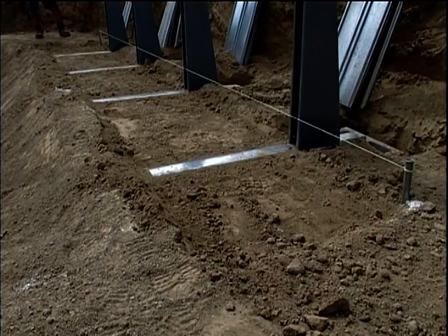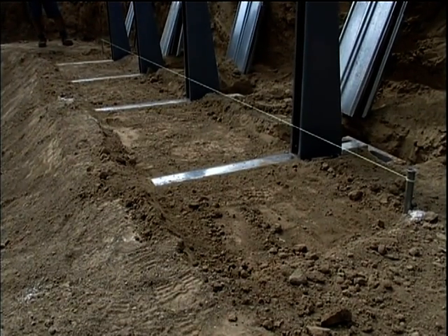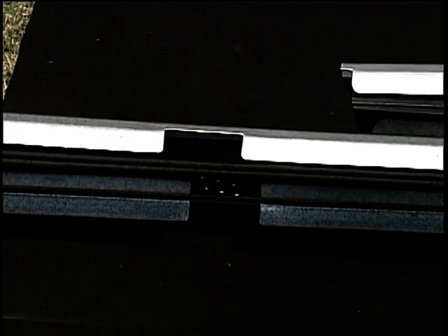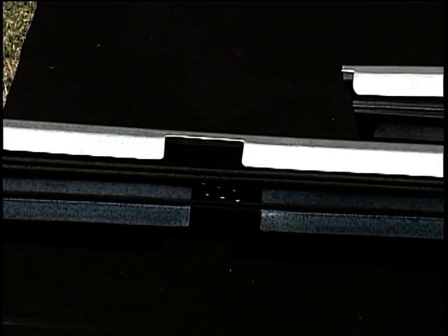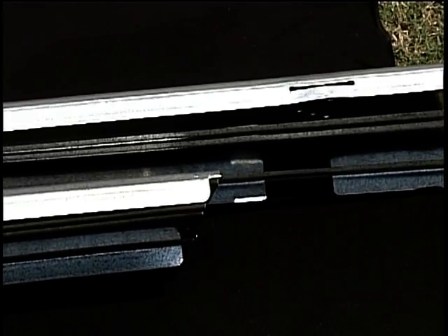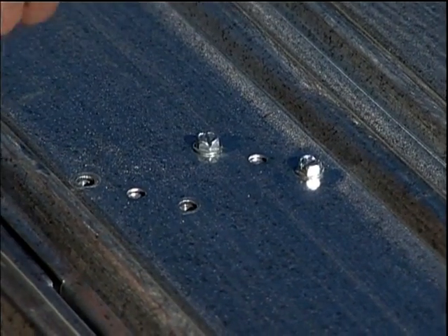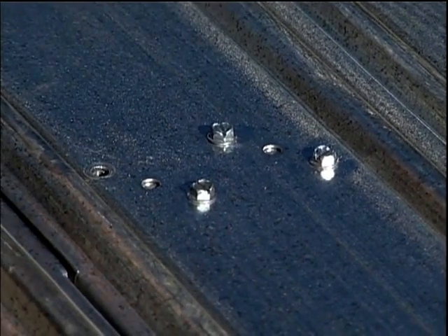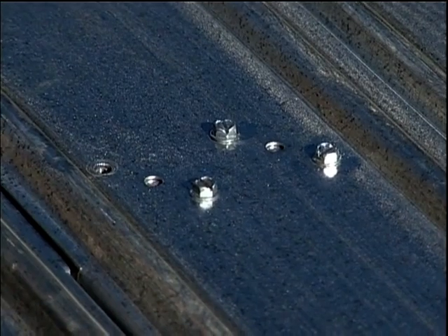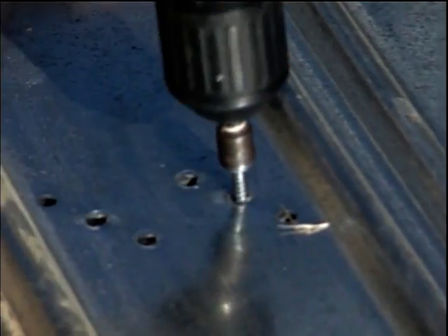With the trench dug and double checking to make sure the trench is level, the next step is to install the pressure pads. Each vertical gets 2 pressure pads, one with a notch at the center and one without. As you will see, there are pressure pads with a double notch out and pressure pads without. Keep in mind that the notched pressure pad always goes closest to the vertical assembly. Fasten the pressure pads to the ground channel with 4 12 by 3/4 inch long screws through the 4 holes in the center of the pressure pad.